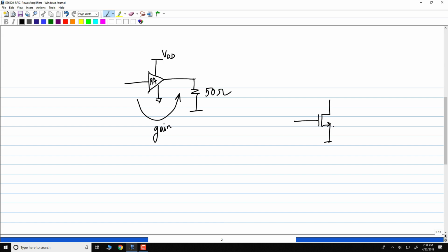This is exactly the point: the minute the load is 50 ohms, right? So you would have seen various structures. I think the ones that you are thinking of giving you more gain are the case where you have something like this, correct? If you have a case like this, it looks like cascode might give you more gain, but remember that you always have the 50 ohm load. So now I'm going to add the blocking capacitor to make sure that the bias is not affected by adding the 50 ohm load. Will a cascode give you more gain than a regular common source? Most probably not. So to start with, it looks like there is no reason to go to a cascode,